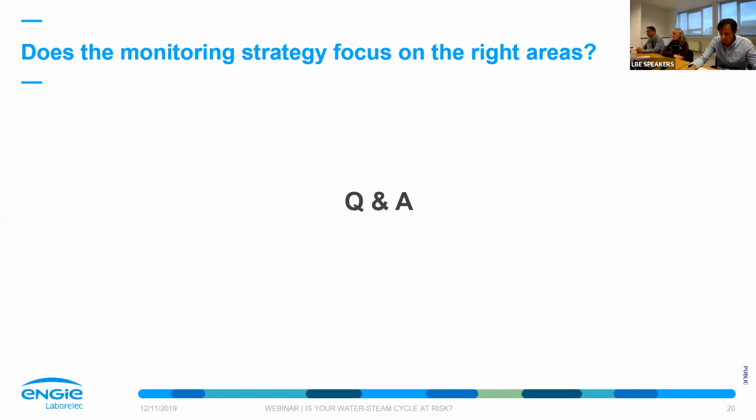Another consideration can be the staffing of your organization. If you have good staffing with a lot of people daily on site, then you can consider caustic soda, because caustic soda is so powerful that when you have an overdosage, you can create caustic gouging in your steam path or whatever.